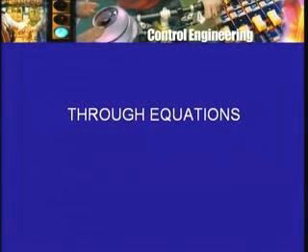But you can set up the analog computer system, that is the op amp circuit, choose the resistor, capacitor values in such a way that there is a correspondence between the output voltages of the several op amps, and between the various mechanical variables like position and velocity of the mechanical system. And usually this is done through the help of equations. It is possible to do such analog modeling without worrying too much about equations.